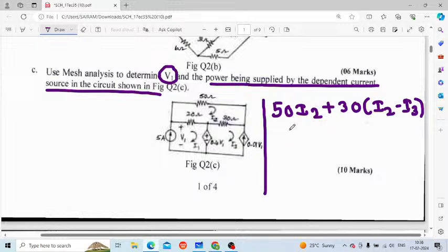Okay? And it is plus 20 into the I2 minus I1, students. Right? You are getting my point. So what did you get to know now? You got to know that I1 is equal to 5 ampere. Then you got to know that there is a V1 present in this 5 ampere. So how to find out V1, you got to know by using the superposition theorem. And I've told you why the superposition theorem, because we need to find V1. Right? You got to know all those.